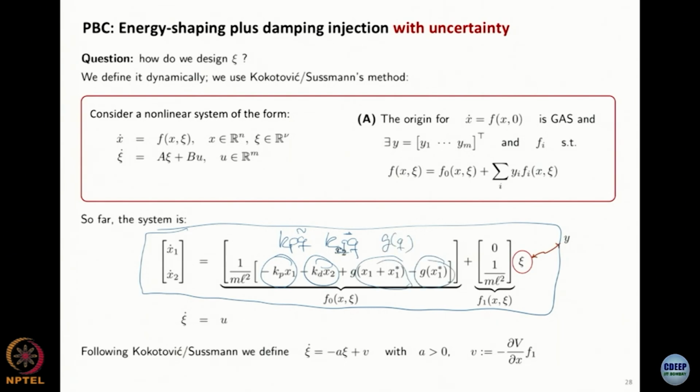When I apply the control with the estimate of the compensation, I will have these equations. So I have psi times a nonlinearity, which in this case is just this constant vector. And here we have this F0, remember, that has to be GAS. But I know that it is GAS because I know how to do things when I know the gravity compensation.